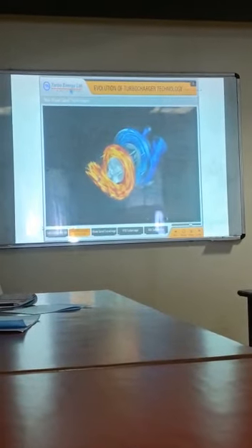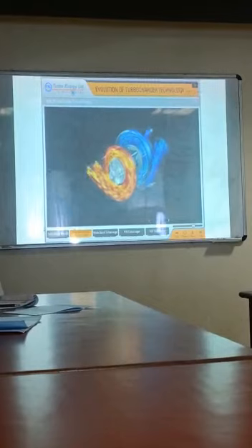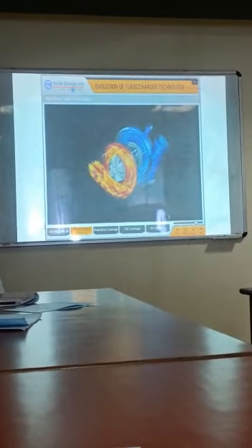With a fixed size of turbine housing, the turbine wheel speed will be maximum when the quantity and temperature of the gas are maximum. The speed of the turbine and compressor wheels increase and decrease based on the quantity of the exhaust gas and its temperature entering the turbine housing.